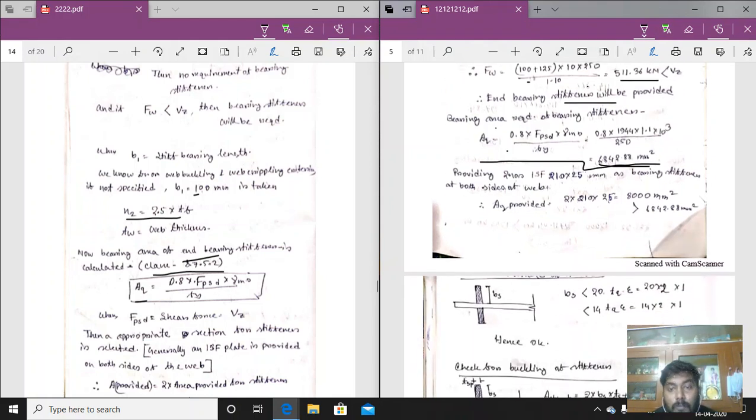Okay, so let us provide two nos ISF 200 into 210 into 25 mm. So 210 mm into 25 mm. Now let us clarify something. I have checked this math also with 200 into 20, but in the lateral torsional buckling criteria, that stiffener fails. So I am assuming a higher value. In the exam, if you get some problems in the lateral torsional buckling, simply say that the design needs to be revised. You don't need to redesign that thing. That's right. The design needs to be revised.